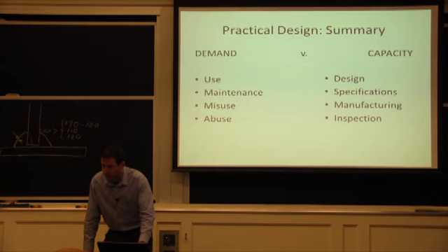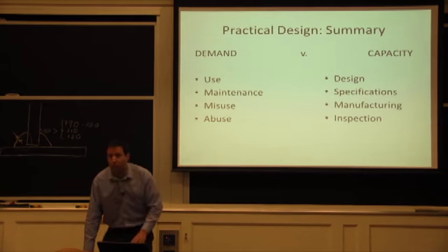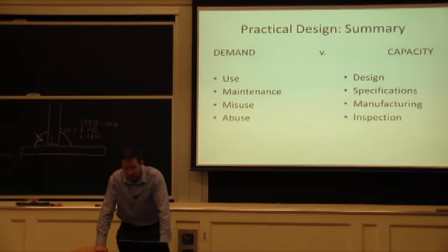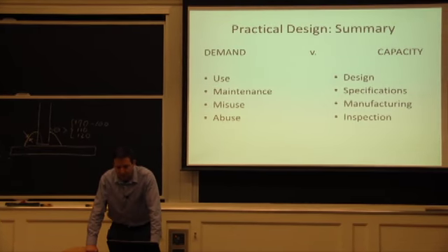We talked about the trailer where we wanted to put the welds away from the highest loaded locations, specifically to rule out manufacturing as affecting the strength. There's still the manufacturing of the wrought steel itself, but that really tends to be consistent as opposed to making bolted connection and making welded connection.